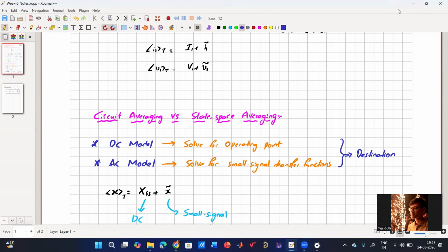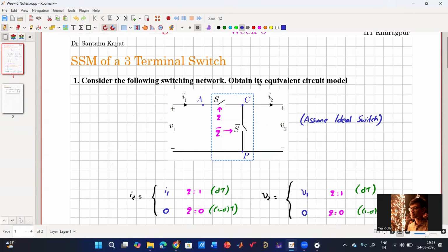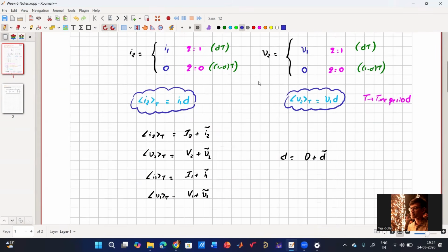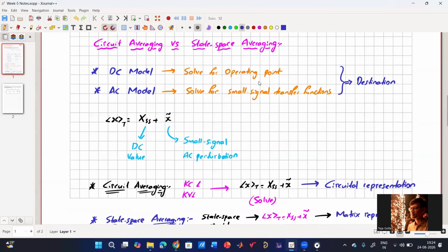In the basic converter we have only one switch, Q equals 1 and Q equals 0. In a non-inverting buck boost, we have 4 switches, and in some other converters, we have even more switches. Then it is not easy to consider the switching configuration and the large signal model, which is a little difficult for someone who is learning controller design. So it is equally important to learn small signal, because although it has model validity limits, it is simpler to understand. Everything will be converted to the S domain. You can use any toolbox in MATLAB, or do pole zero cancellation yourself to design the controller, which was our overall main objective.